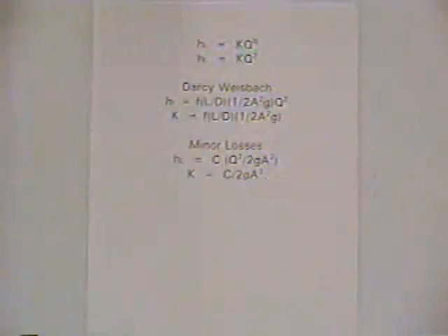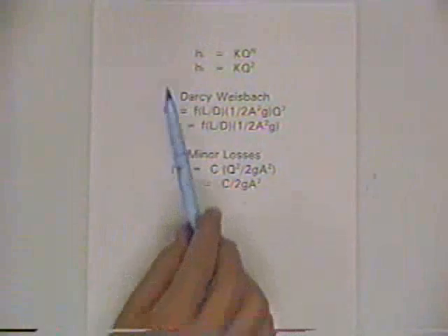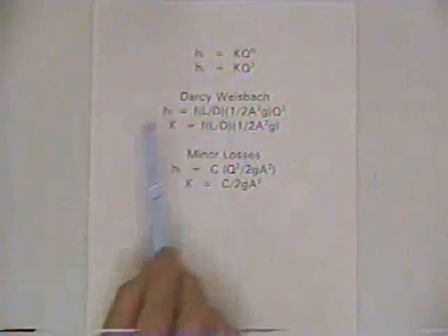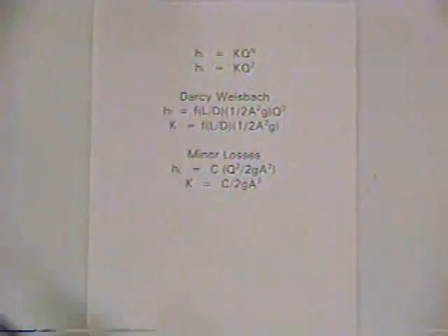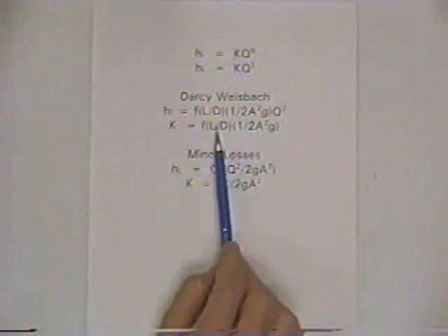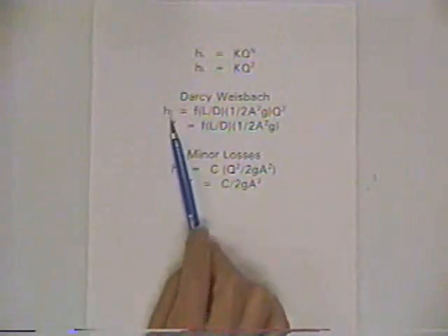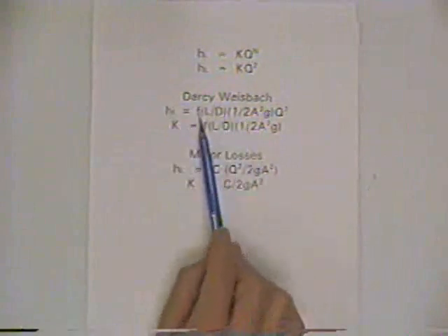We've looked at problems dealing with one pipe, and let's think just a bit about pipe systems, pressure conduit systems that entail more than one pipe. To do that, it's going to be convenient to express a relationship between head loss and discharge, and we've worked with this already. In Darcy-Weisbach, for frictional head losses in a pipe, we looked at f for frictional head losses.